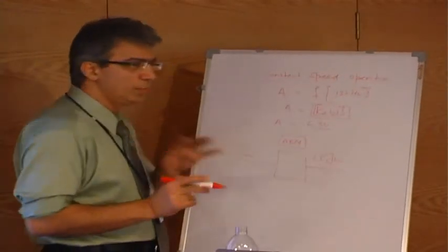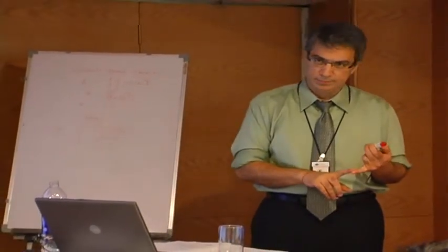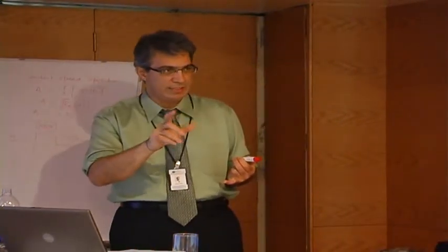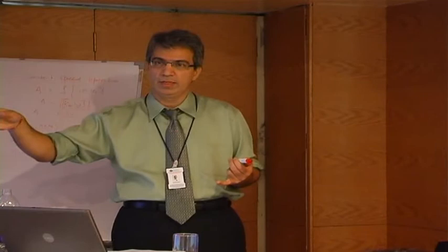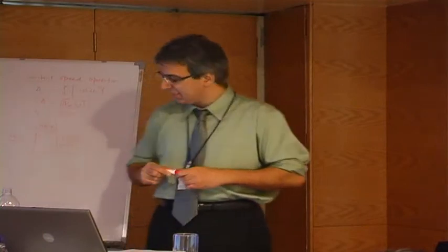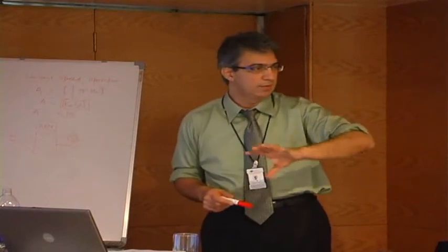So in this particular constant speed model, we want to illustrate ideal components. We want to illustrate the PWM, which we're going to talk about in a minute. The PWM function is critical. And I think what we have is quite beautiful. The ideal switch, the ideal diode. Those are the three components which we use quite extensively in building our models, and those are what I call convergence robust. It's quite easy. The same model you can use for variable speed as well.